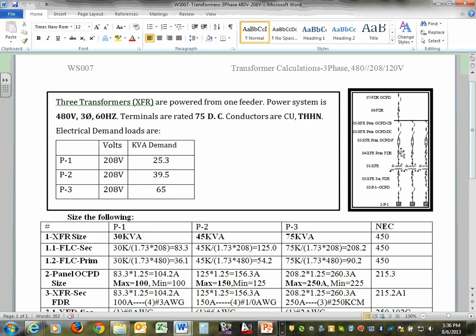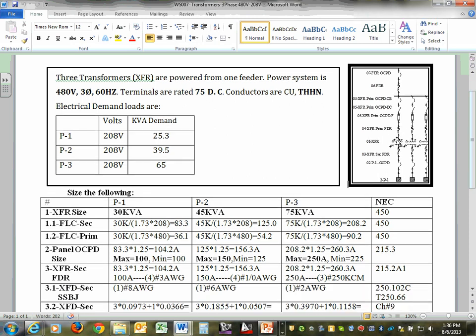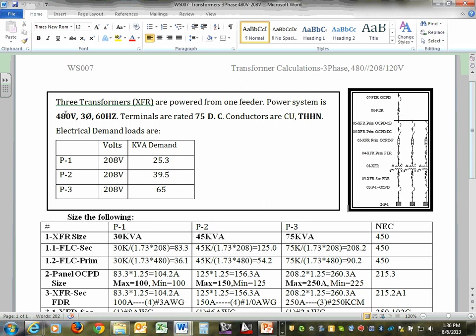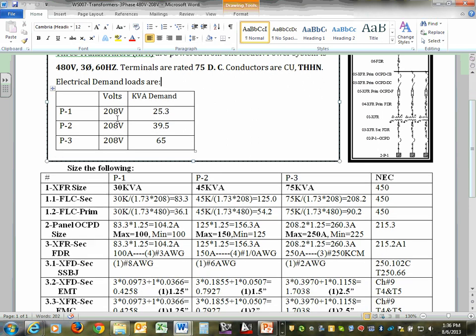Exactly like we did, if you guys remember, the chillers and so forth, exactly like we did the chillers. Here's my assumption: all of them are fed at 480. Or look at the terminals, which is 99.9% of the time you're right, the lugs are rated for 75. So when they size, I'm using THHN. Okay, now here's where I think it's very important.